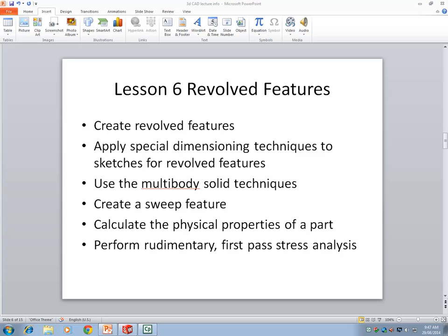If you can't find an axis, if there is no axis in your sketch, you can always create a new axis using your planes or 2 points on the model space. I told you about that last lecture, how to use reference geometry. The objective here would be to also apply some special dimensioning technique, especially with the diameter, inferring the diameter, placing it on the model space.